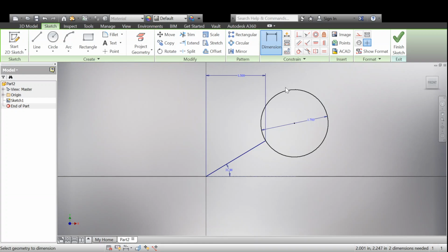It moved, right? Because what did we do earlier? We trimmed it. I agree with that, Joe. But before that, when we created the circle, how did we create the circle to start? Okay, correct. Before that, we set the endpoint of the line equal to the center of the circle. Remember earlier, we chose the center of the circle to be the endpoint of that line. So it was working as a function of the line's length, so the circle is still moving with respect to that.